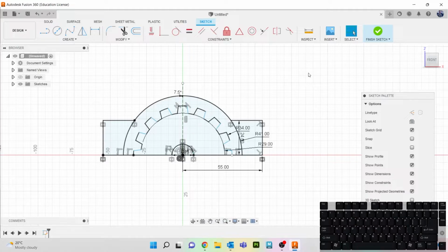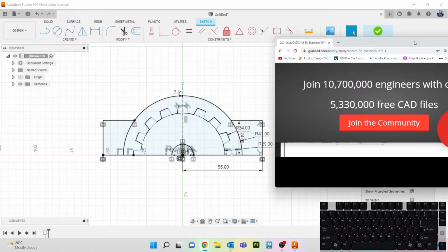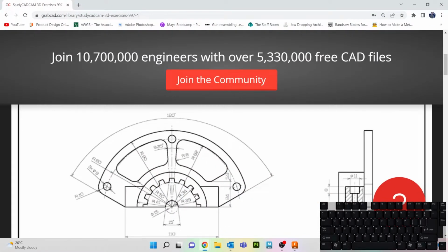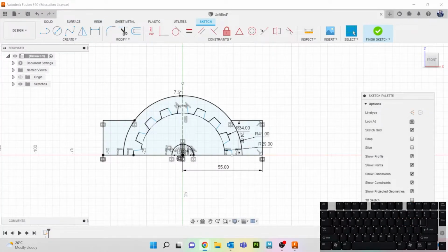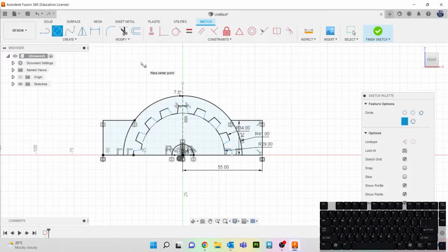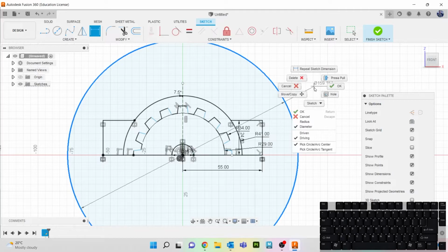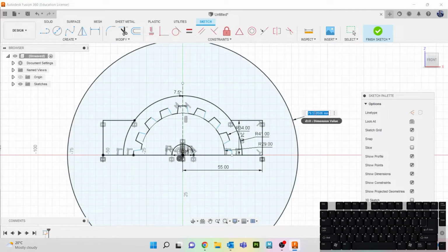Next, let's have a look at getting the overall shape done. So bear with me, I'm probably going to go quiet for a second while I start looking and trying to figure out the next sort of shapes to do. So this one has a radius of 90, so let's put that in. So let's do circle, radius again, so let's right click, radius 90.